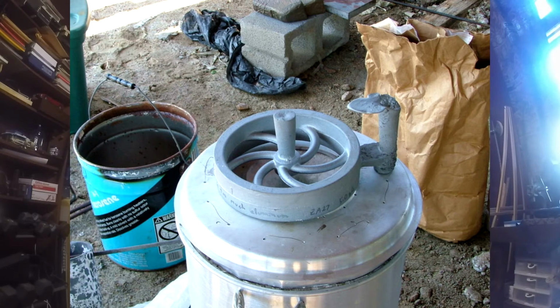It might have been right there where the in-gate was attached. It might have just stayed right there, or it might have been pushed throughout the mold cavity and got lodged into the skin of that casting, which is a casting defect. It's no longer solid metal at those points where you have the dross. It's closer to being rust than it is to being solid metal.